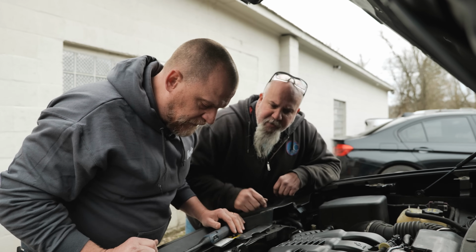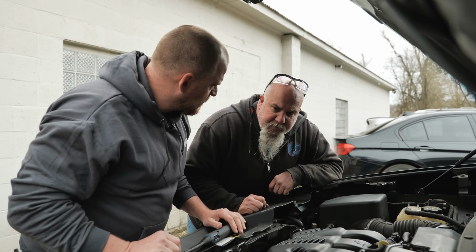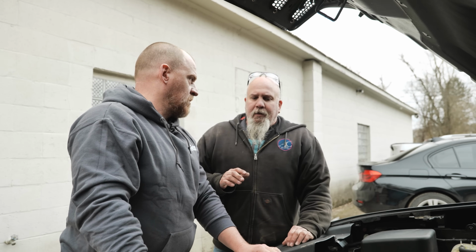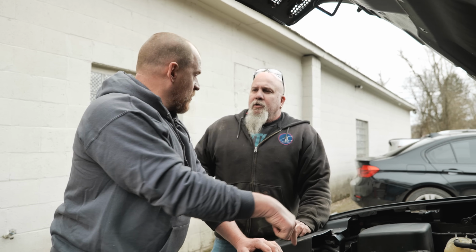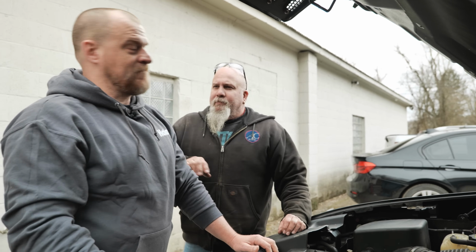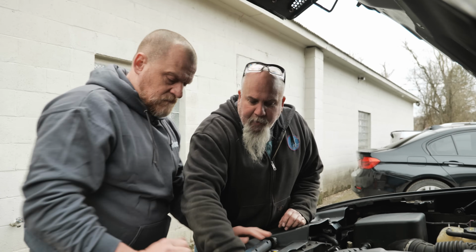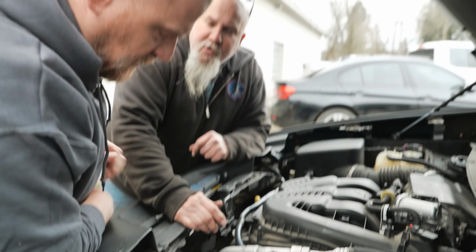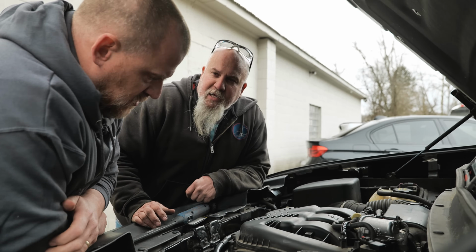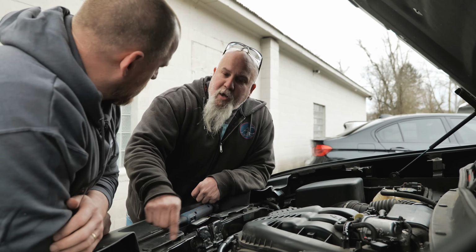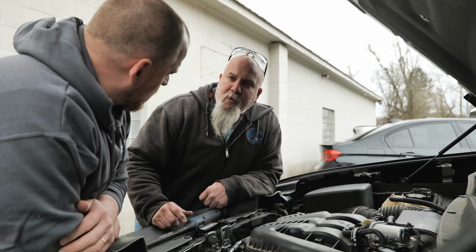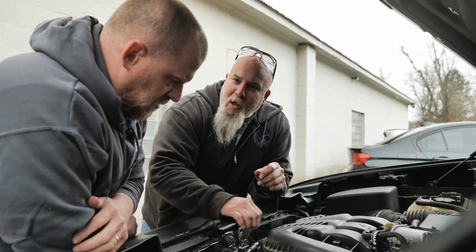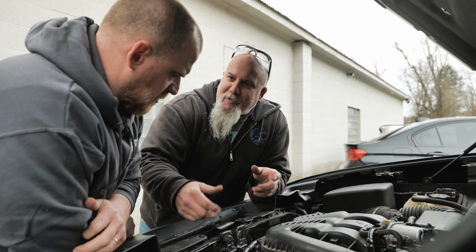This looks brand new. Yeah, this one just changed, like a week or so ago. When did this problem start? I think after this hose rupture. So what happened with that hose? The factory hose has a plastic nipple on the radiator hose itself. They discontinued it, they don't sell that no more, so you have to buy a new hose with this tube. Change the tube. So what he had, this is what he had to get her home. He put a hose over top of there and over top the radiator and clamped it.